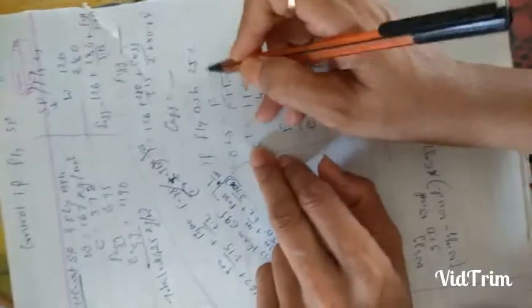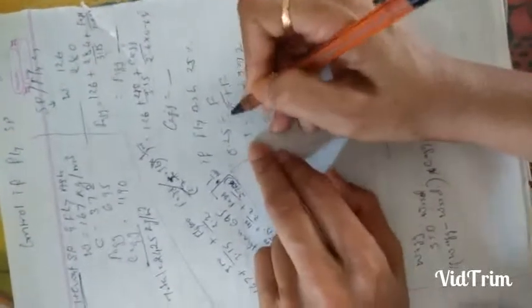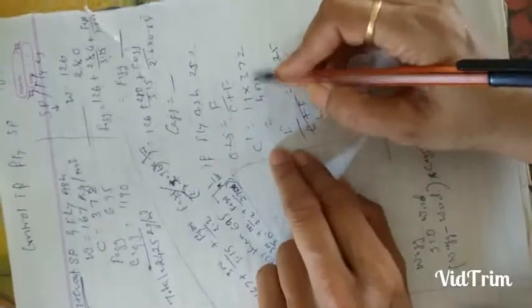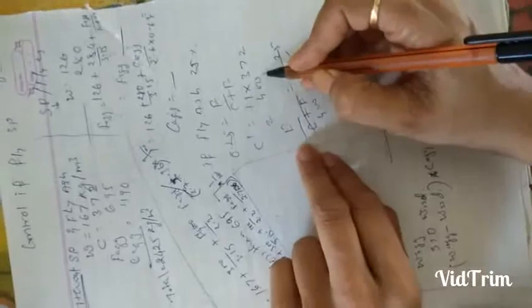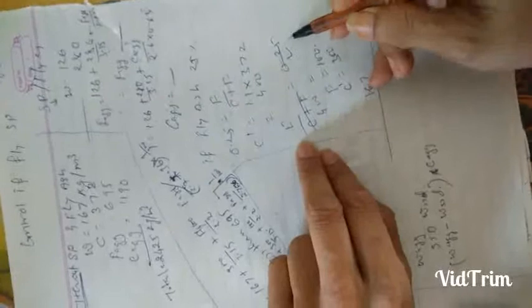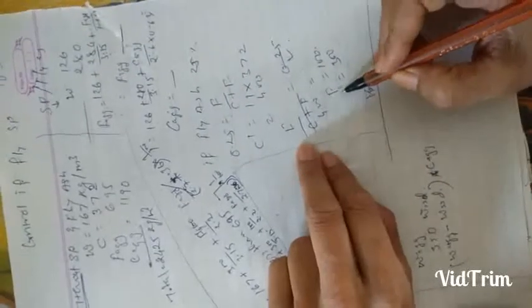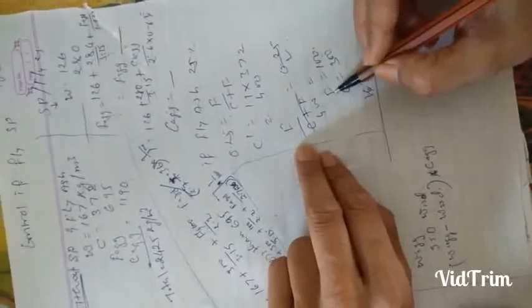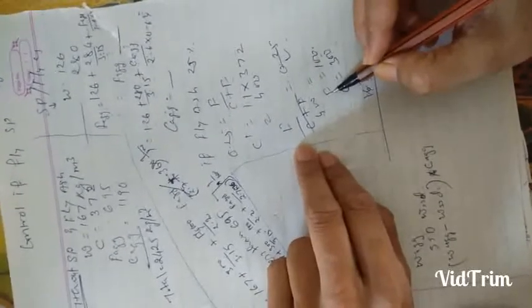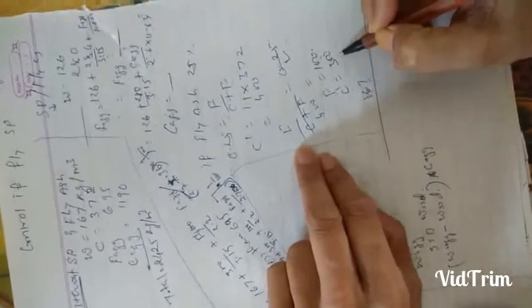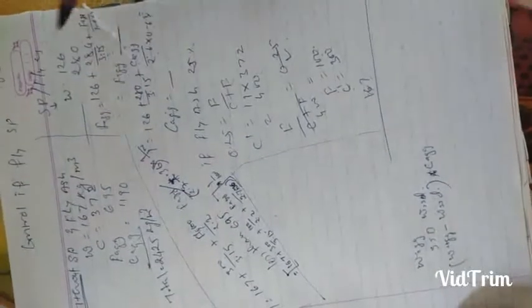If fly ash is 25%, then 0.25 is equal to F upon C plus F. Then C dash is equal to 1.1 into 372, which is equal to 400. So F upon 400 is equal to 0.25, right? So F is equal to 100. So your fly ash content will be 100 and C dash is equal to 300. So these are the contents. Now if we are using superplasticizer,